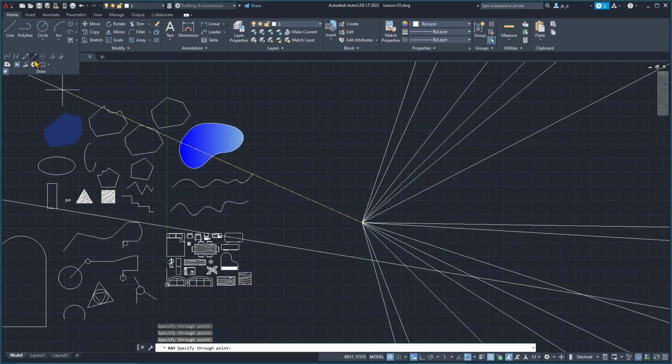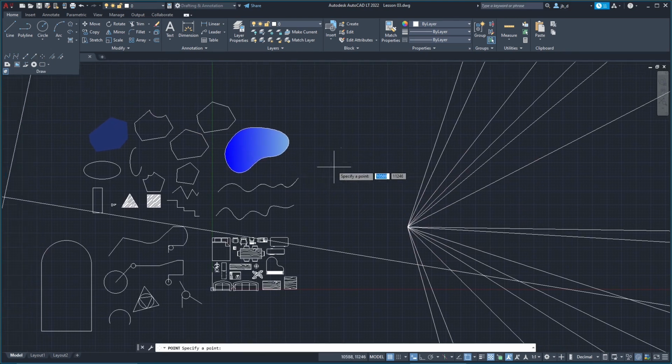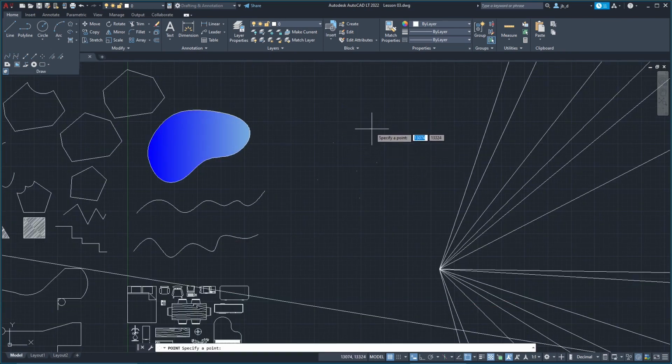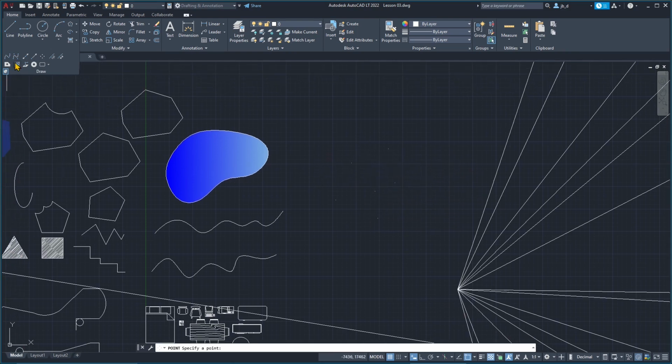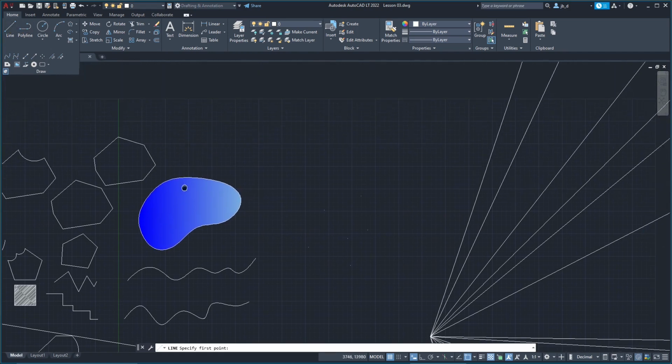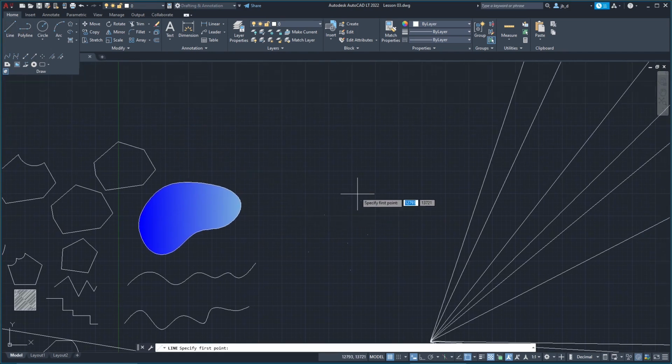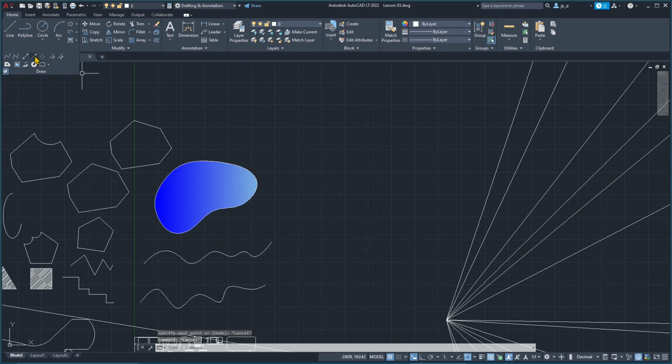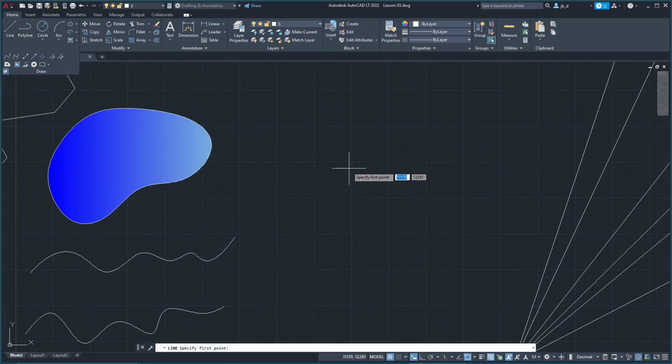Let's proceed here. We have points. So points are mono-dimensional, so they are only 1D. So we can use them as a snapping point using the snap, but you need to activate the snap to the point. Right now we're just going to see what they are real quick, but remember that they can be used as standalone vertices, and then you can use the line or the polyline to fit in some shape.